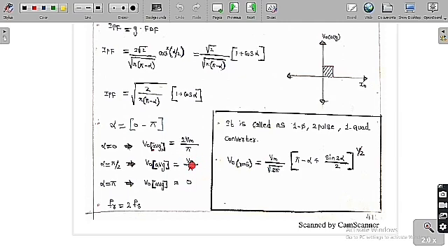Here only positive values we are going to get. The load current is always positive, it cannot be negative. So if you take the coordinates I0 and V0 average, V0 is always positive and I0 is also positive, so it is only first quadrant operation. The semi-converter can only operate in the first quadrant, whereas the full bridge converter can operate in both the first quadrant and the fourth quadrant.